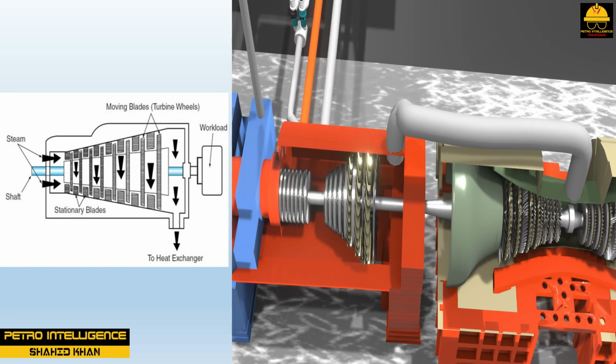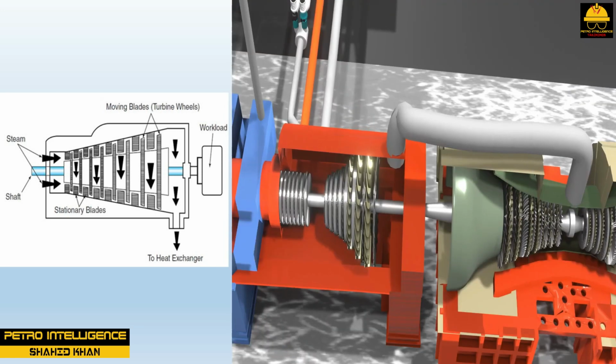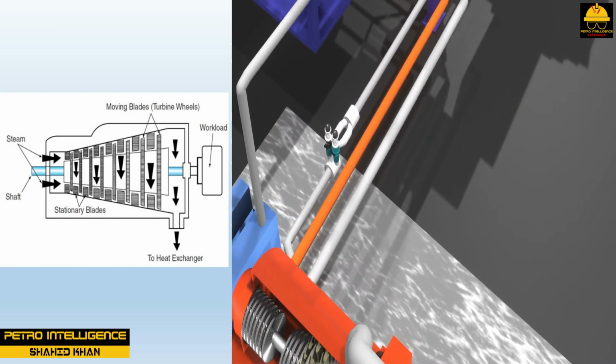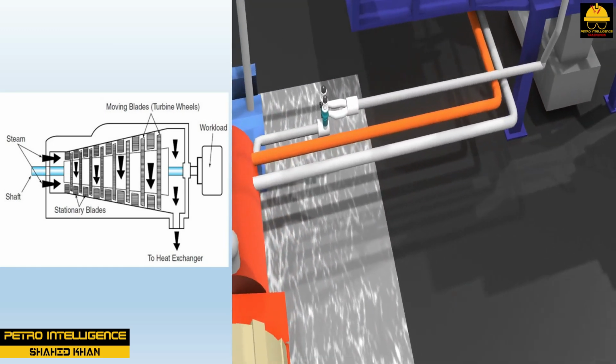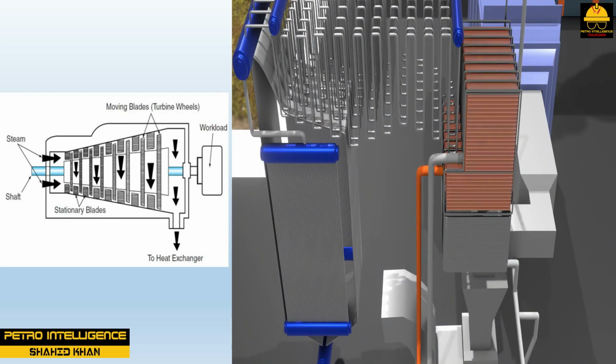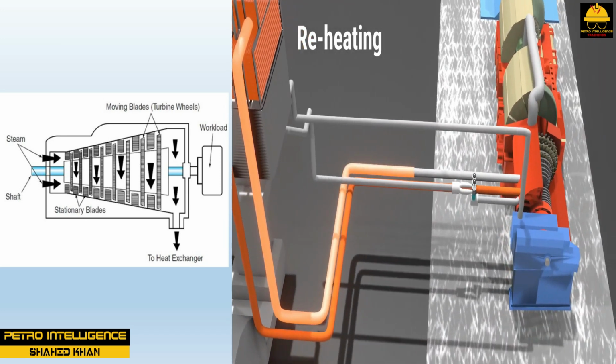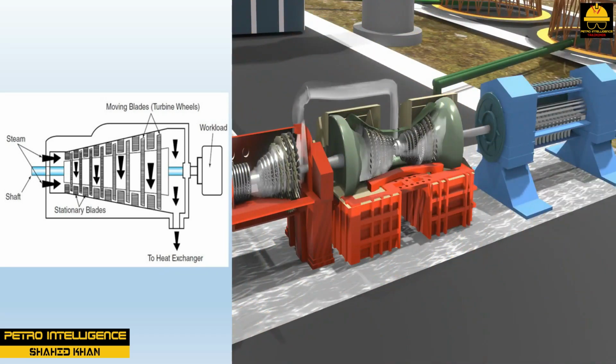High-pressure steam is admitted slowly into a turbine to warm it up and remove condensate, that is, moisture produced by condensation. Steam turbines are used to drive the electric generators in modern power plants. A multi-stage steam turbine is considered to be one of the world's most powerful engines. Modern turbine technology includes 50 or more stages linked along a horizontal shaft.